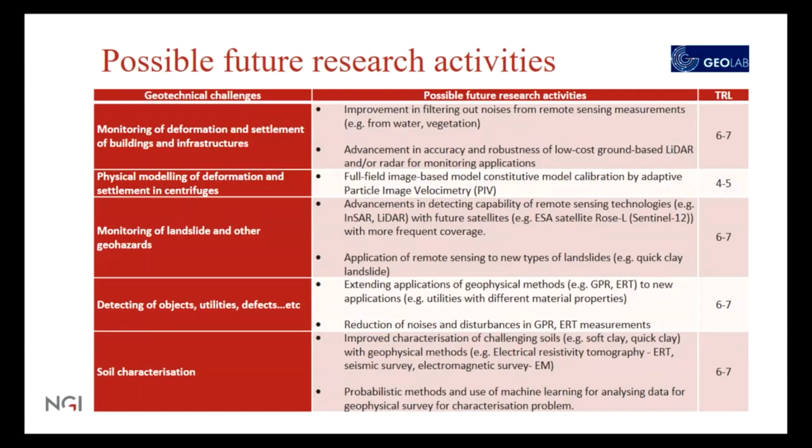Oh, Yanis, yeah. It's not really burning, but I can ask something. Thank you for a very nice presentation. The various geophysical methods that you showed, usually you can measure, let's say, shear wave velocity, VS or VP. Is it possible just with methods like this to get additional information related to strength? Or do we always need some boreholes also? I think he can reply to you because I really don't know.